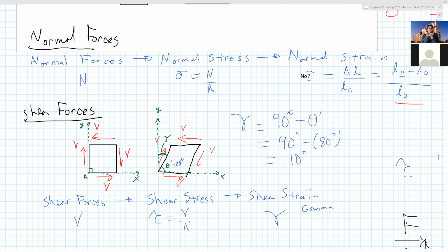Try to get gas or water. When you shear water, get some water in your hand, do it now, preferably over your keyboard. Get water and shear it, put a force on it. Will it bounce back? It's not. That's why when you look at water pressure, the only type of pressure you have is hydrostatic pressure, which is forces in the normal directions, not shear, because water cannot sustain shear.